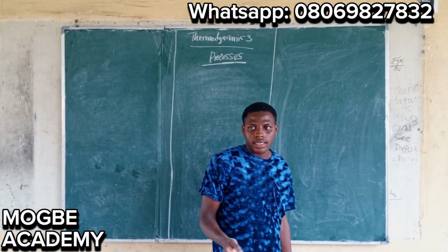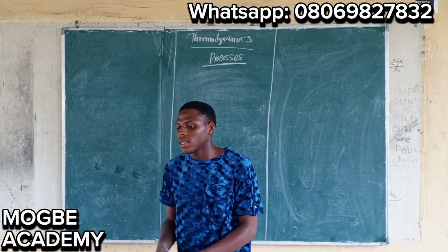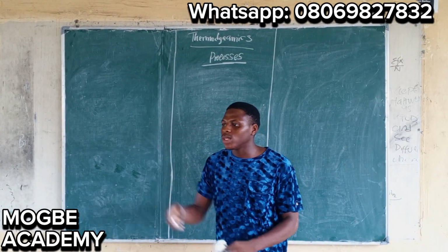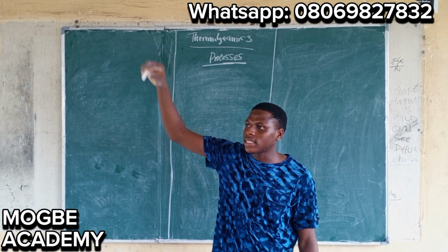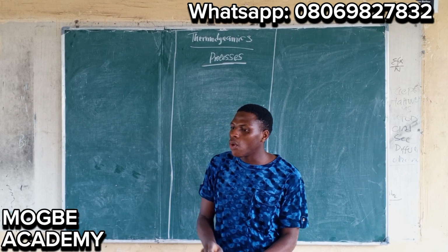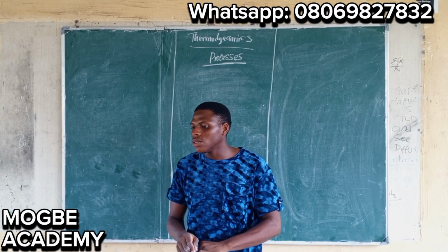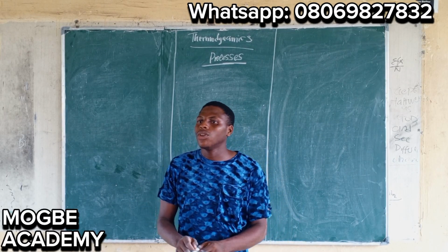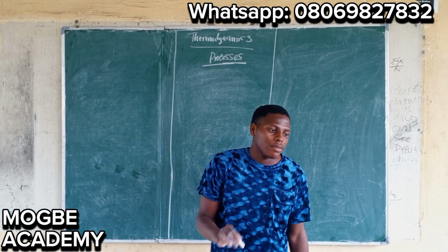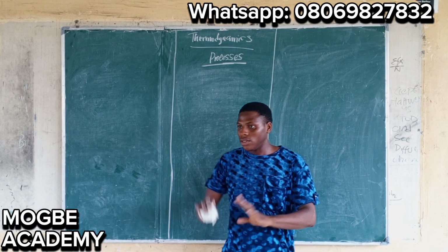When we are given mass, if mass is given in your question, then you use your mass to multiply everything on that table I gave you. Whether your flow work, your non-flow work, your shaft work, your change in energy, your heat interaction, your change in enthalpy, or your change in entropy. You use your mass to multiply everything you have there if the mass is given. But if your mass is not given, you leave it like that.